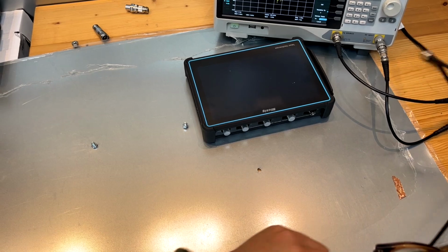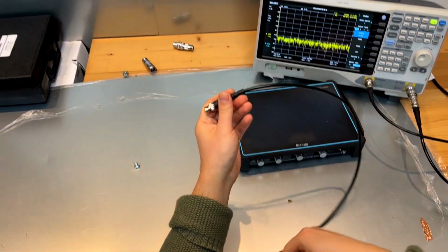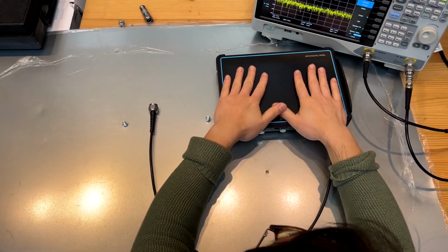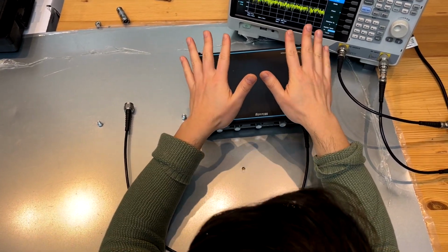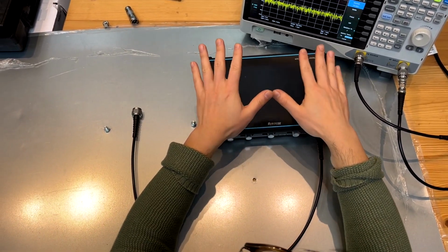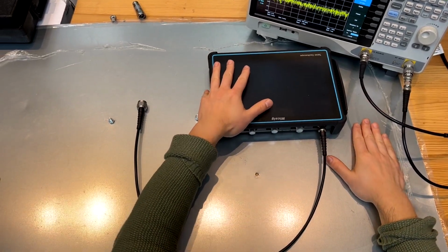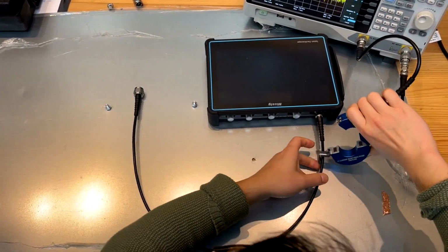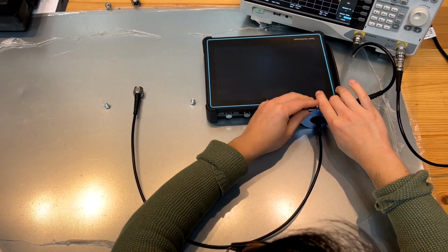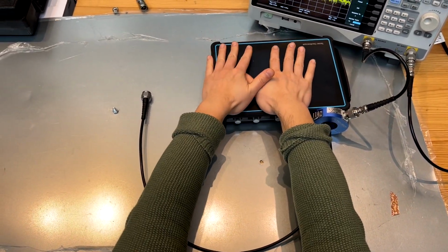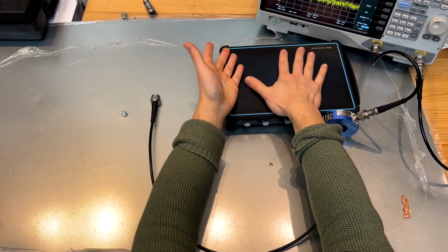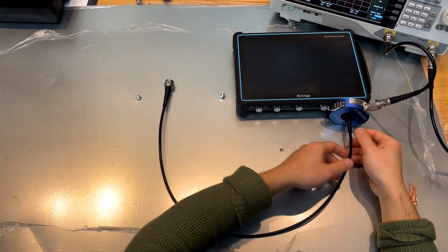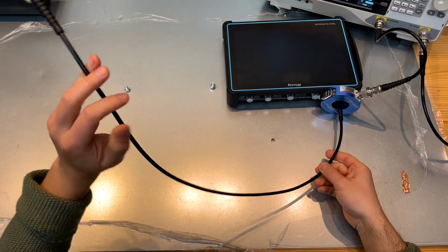I connect the same coaxial cable from the previous demonstration to this point. And this is a dummy unit. It's not powered. It just provides a relatively low impedance to this common ground now. Again, I'm going to inject noise from this probe, and you can imagine this is a unit, and you will inevitably have some common mode noise, right? And this represents the common mode noise getting out of the system and traveling on this cable structure, right?